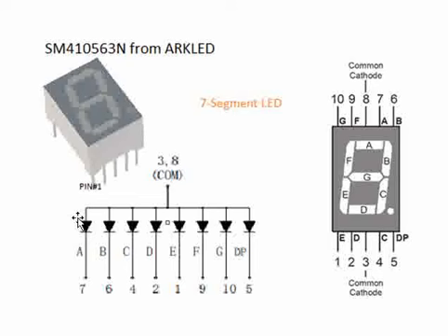To light up a particular LED in this segment display, you have to make this pin low such that the current passes from the supply provided to COM through this display, and then it powers up. That means you have to give a voltage that is more than the forward voltage of this diode. So that is how you have to operate this 7-segment display.